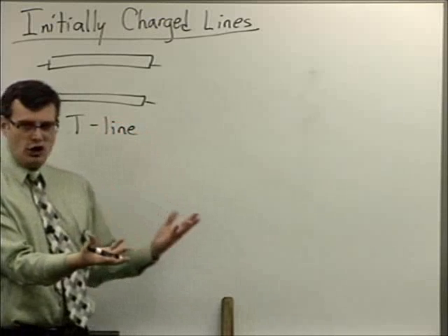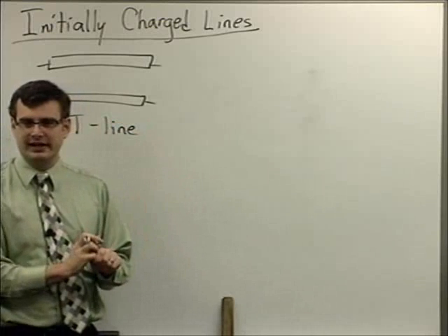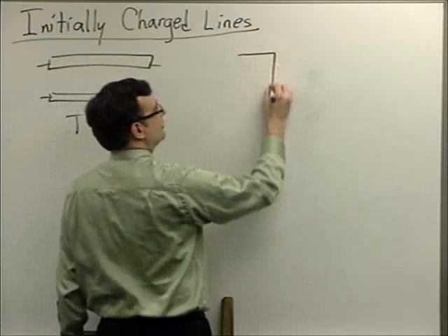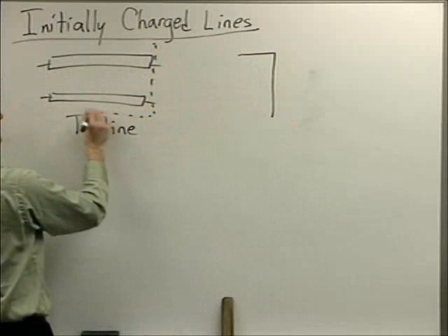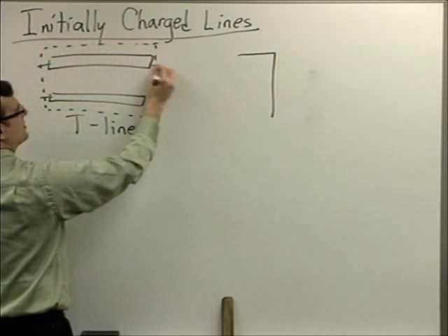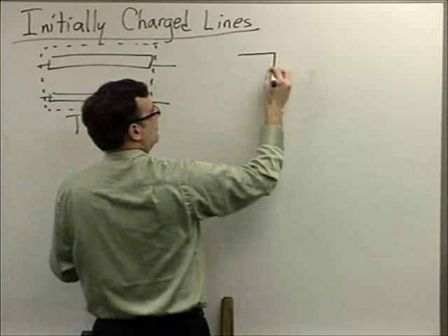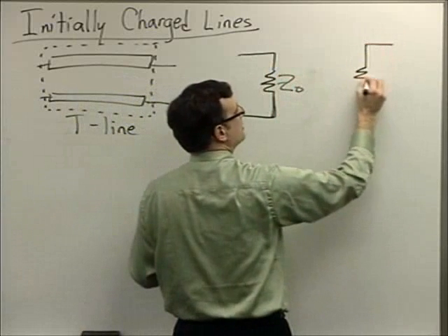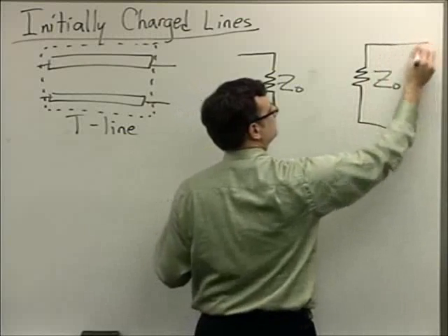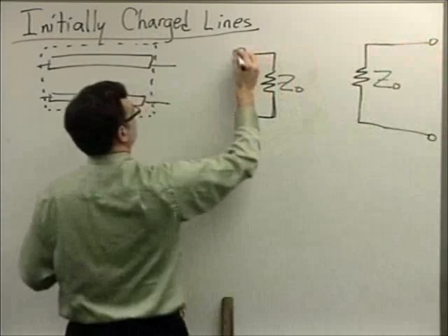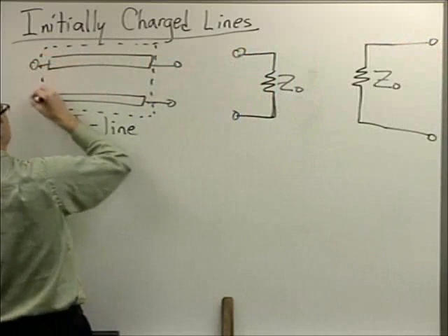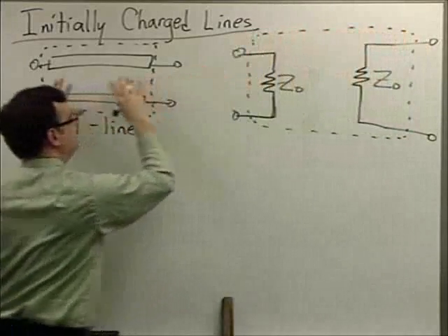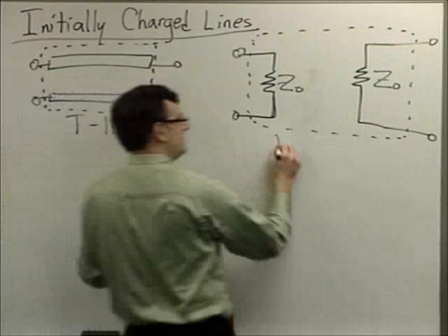We said when we have a discharged transmission line, there are no voltages and currents on it, and we're interfacing it with a circuit that maybe suddenly energizes it. What does it look like? We can replace this, and I'll draw a dotted box around here just to denote where we're severing everything and what we're replacing. We can replace that with 2 Z0 resistors. Make nice and pretty terminal circles. And so this box gets cut and pasted into this box in your circuit analysis when you have a discharged line.